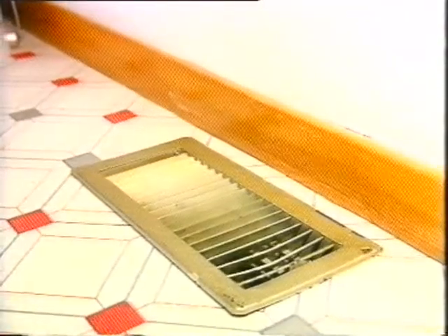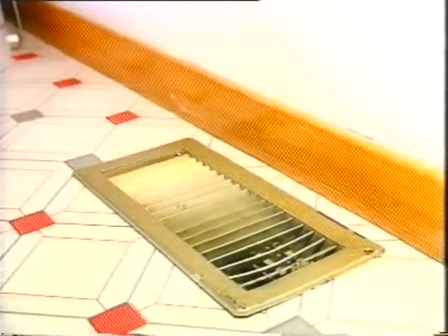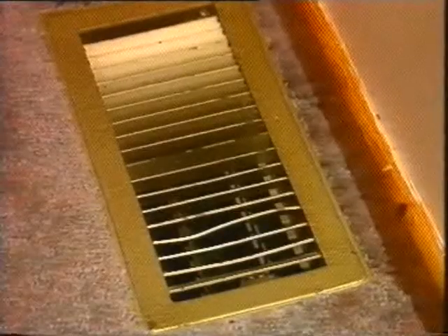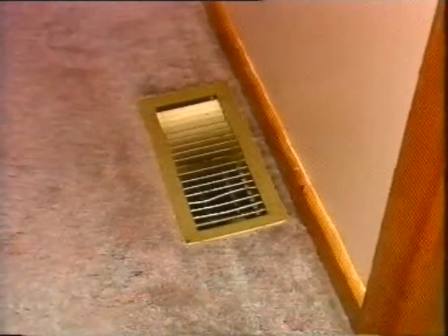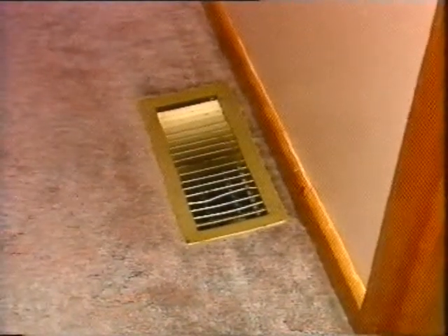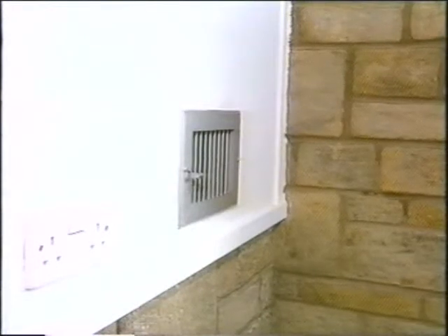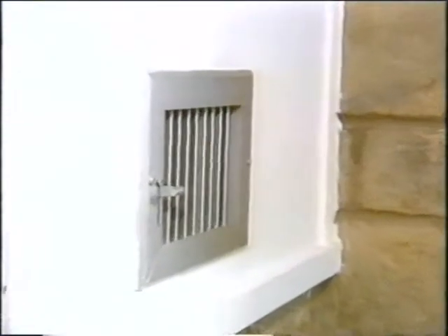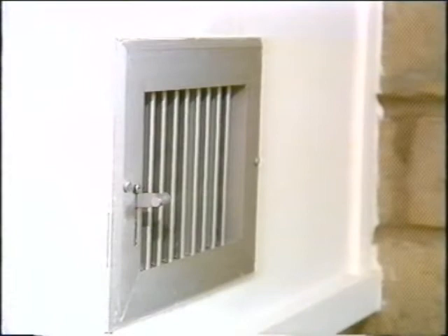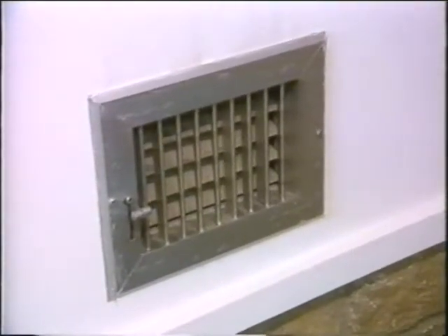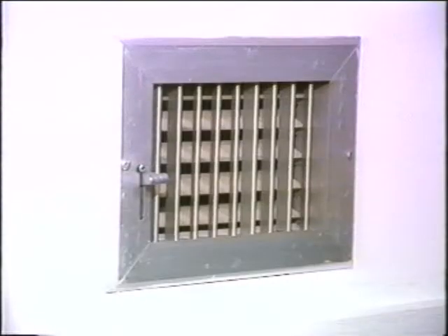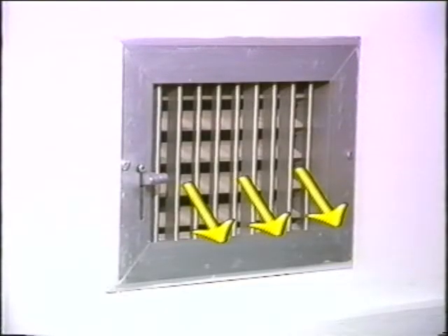The warm air's delivered to rooms via diffusers or registers. Depending on what sort of room it is, diffusers can be located in floors or ceilings. Registers are fitted in side walls. They've got distribution vanes to deflect the air flow so that it covers the whole room. They should be installed so that their closable blades are directing the air downwards.